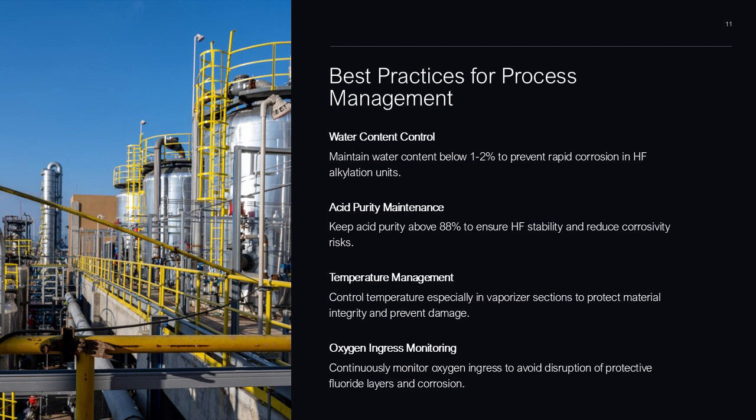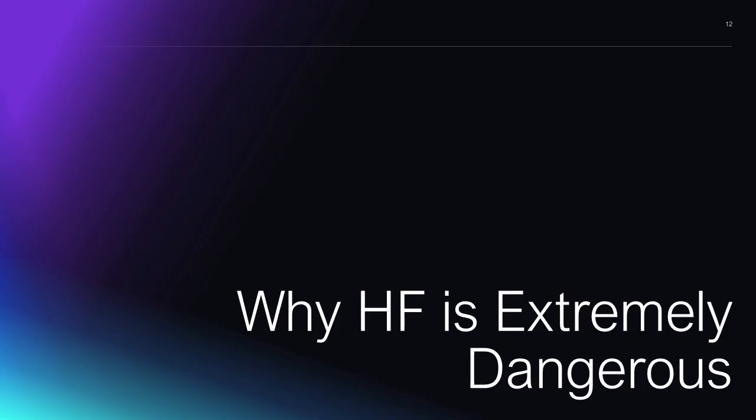Continuous monitoring for oxygen ingress is also critical, as oxygen contamination disrupts protective fluoride layers and promotes aggressive attack. Implementing these controls, combined with regular inspection and predictive modeling tools, ensures safe and efficient operation in HF service environments. Why hydrofluoric acid is extremely dangerous: dual threat, corrosivity and toxicity.